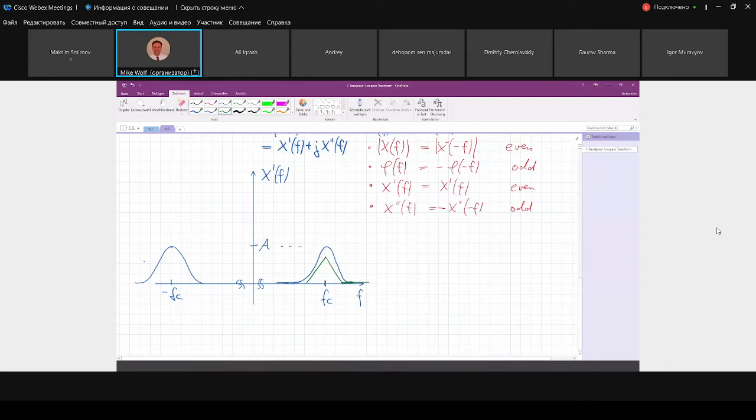We need to ensure in our figure that the imaginary part, so this is X2 prime, is an odd function. No question about this. Therefore, here on the left-hand side, I need to draw it like this. Because it's the imaginary spectrum, and we know our time domain signal is real, it has to look like this if we know the right-hand side. So this is the imaginary part. So here B.